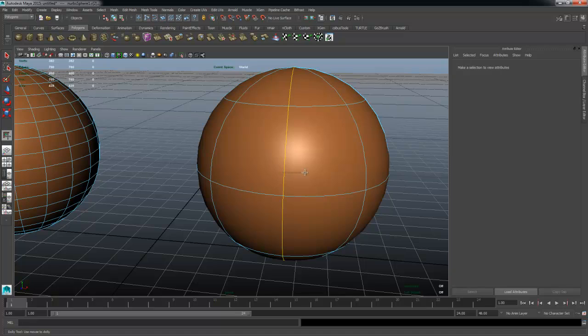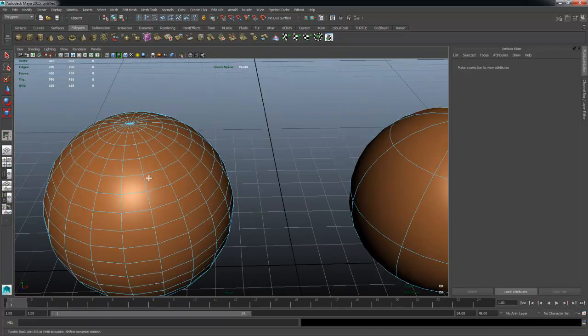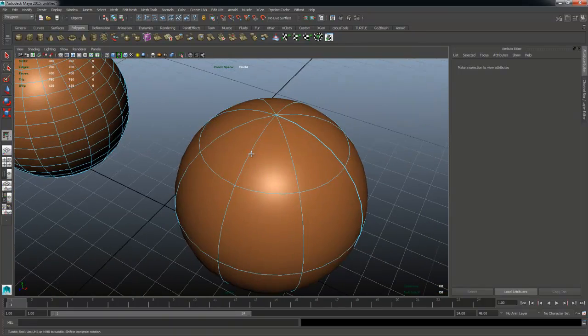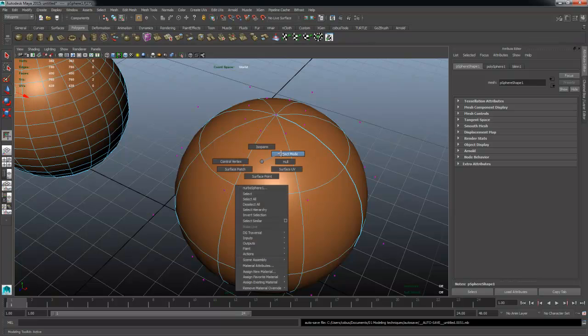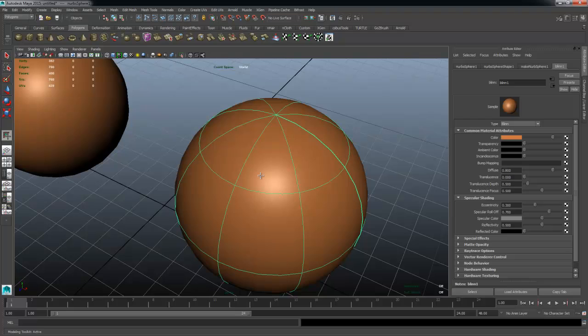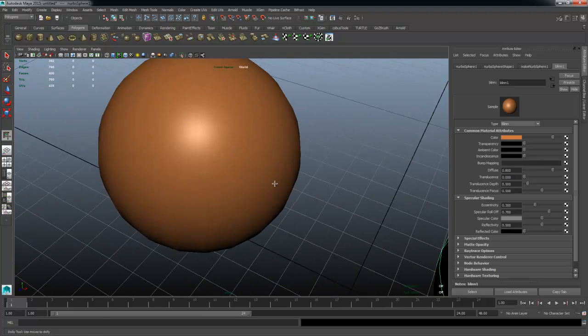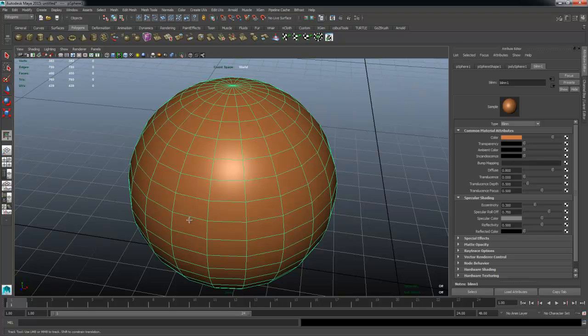So the cool thing is we can essentially add additional isoparms on the model like we would do with the edges. What this means is that an isoparm is built on a curve type of algorithm, and that means we can actually make use of the curve tools in here to generate certain shapes on the model. So if I were to create some sort of a custom shape, I can then project that onto the surface and then add that as part of the geometry, or the mathematics that makes up the curved surface. On the other hand, if we had to do it on a polygon model, you're going to run into some issues. You're going to have to cut through certain edge components and face components to essentially make out this new shape, and that's going to end up with a lot more custom geometry or extra unnecessary points on the mesh that you have to clean up and deal with.